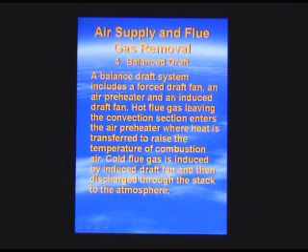Balanced draft. There's a picture of this toward the end where we actually have a forced draft and an induced draft fan. This is used a lot of times where you have a heat recovery coil in the stack to preheat the combustion air. This is an attempt to improve the efficiency of the burner, or of the overall performance of the heater.